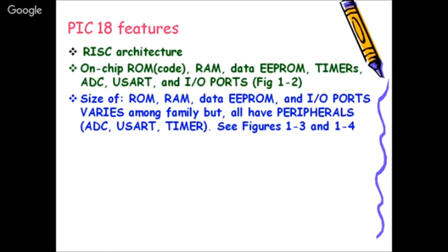If your program counter is 21 bits wide, that means it can go up to 2 megabytes, with 8-bit locations. Because to access your data, whether data or code, what you need firstly is the address. When you address that location, then you can access it. So particularly in the case of the PIC family, the program counter is 21 bits wide, and the on-chip memory can go from as small as some kilobytes to 2 megabytes.